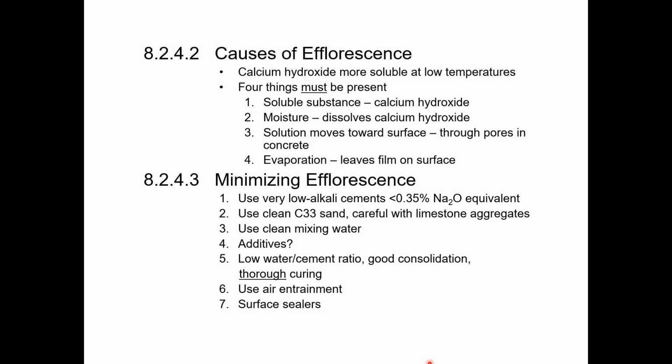You're really just pushing the tolerance issue down the line further, right? And so now you've got a tolerance issue with how thick your topping slab is. And by the way, that topping concrete weighs something, right?